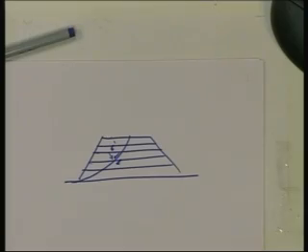On the other hand, if you take a slightly longer duration of the earth dam, during its lifetime the reservoir gets filled or emptied depending upon whether it is a monsoon season or it is a season for irrigation for cropping. So, there is a seasonal variation of the water level behind the earth dam in the reservoir, and if this water level goes down rapidly for any reason, then again it is a converse of what happened during the construction.